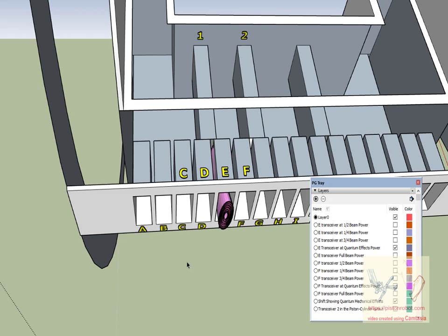And there's no way in the future to know when that's going to happen other than to predict the future. One of the things the city could do would be to go to the stadium and say, please tell us what your ticket sales are, because the magnitude of the ticket sales can be used to generate an opinion about how much sewerage flow is going to happen when the event happens.